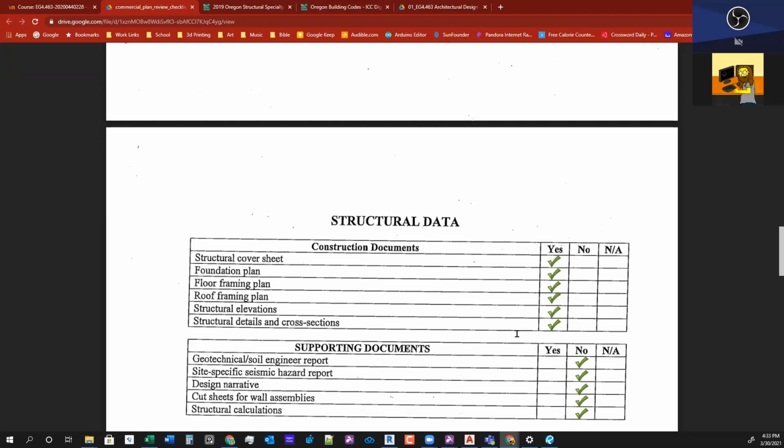So we're going to have two different models. We're going to create an architectural model, and we're also going to create a structural model. And when you do that, it's good to link them into one another, so that when you have your architecture model, you'll link in the structural model, so you can see where all the beams and the columns, any brace framing, shear walls, where the slabs are, slab thickness, because they're going to design all that.